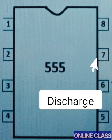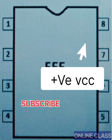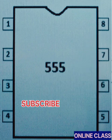Number 7, discharge. Open collector output which may discharge a capacitor between intervals in phase with output. Pin number 8, VCC. Positive supply voltage which is usually between 3 and 15 volt depending on the variations. This is the brief study of 555 timer.